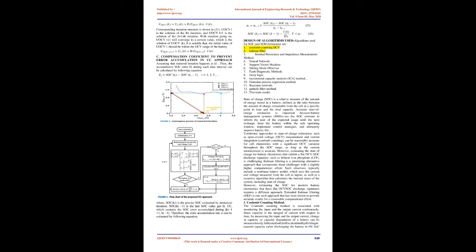Generally, if the battery model is precise, model-based SOC estimation approaches, such as EKF and UKF, perform well without accumulative error. However, the accuracy of the model will be reduced at the unsteady state of a battery, and model-based SOC estimation approaches have heavy calculation [16, 19, 34]. Hence, in the proposed approach, the CC approach is still employed at unsteady state, and numerical iteration based on the battery model is proposed to correct the SOC value at steady state.